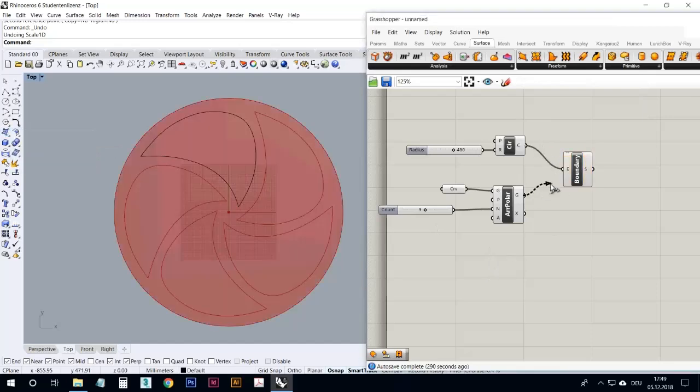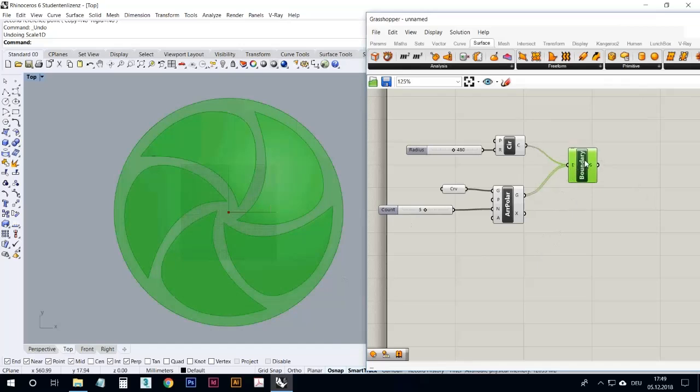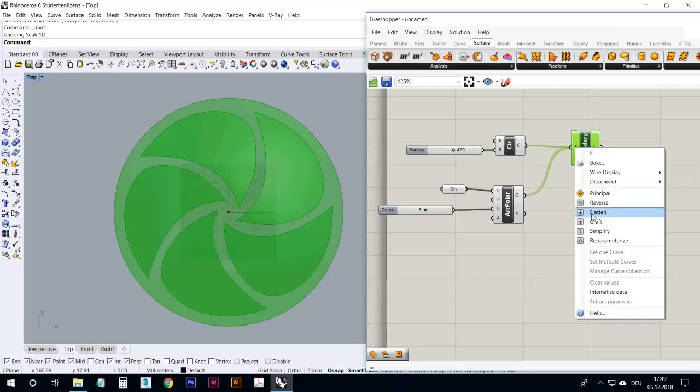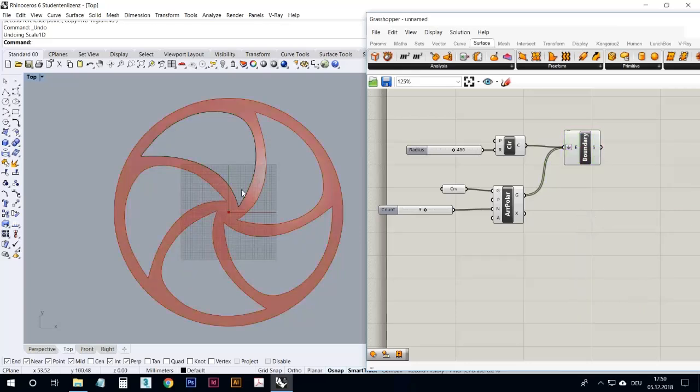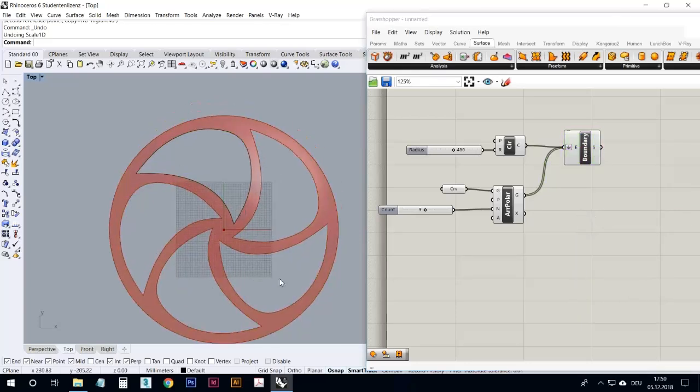So you add this by holding shift, and what happens now? Well, it's actually building 6 surfaces because we told it to do that. But if we do, it's because it's different lists, right? Again, so there's one list with this 5 and one list with this surface circle here. But if we flatten, then it will become one list, and then Grasshopper would automatically make the holes. So there you have the shape that we're talking about, that we're after.